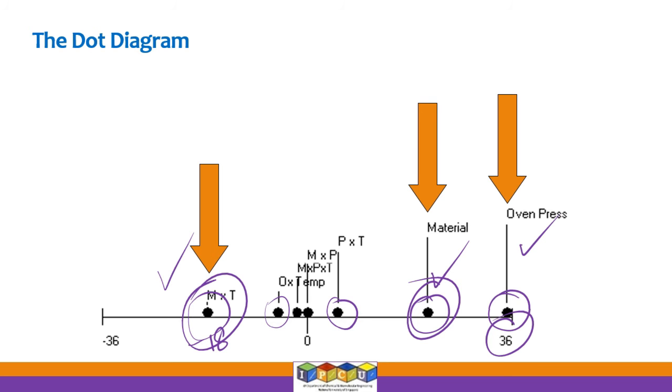So we are sometimes interested in sensitivities or gains being high. Sometimes we want the sensitivities to be low or the gains to be low. When we are talking about a disturbance, we want its sensitivity to be low because we do not want a small amount of disturbance causing a big change in the output. That is something we don't like.